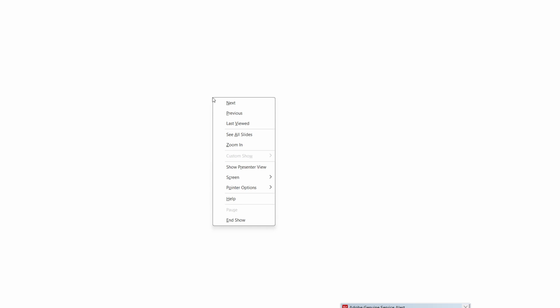As we saw, we cannot always directly use a capacitor. A pure capacitor might not give us a good fit, because it might be a depressed circle. In that case, if you use a pure capacitor to fit the given spectrum, it might not fit well. So we'll use a constant phase element. That is what CPE is.